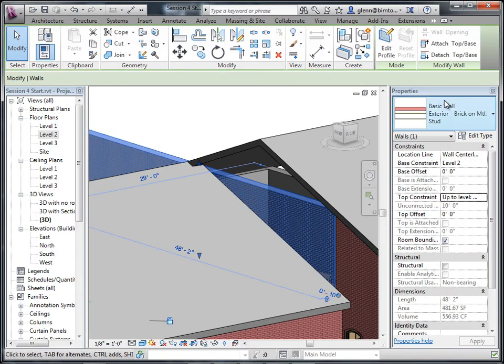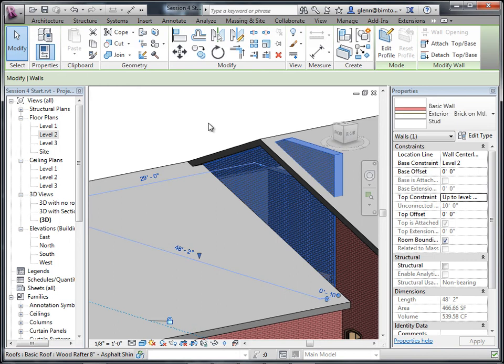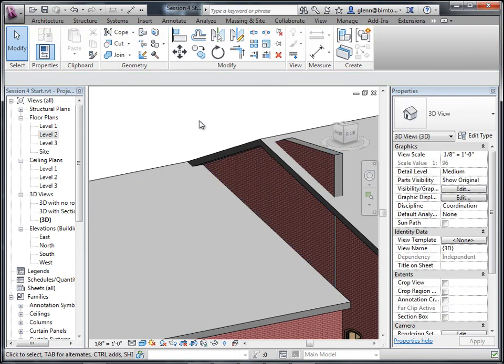One thing we could do is, let's attach this roof to that roof. Okay, did a pretty good job. Not 100% yet, but it did a pretty good job. So let's kind of keep talking about it. Just when you attach roofs, a lot of times you'll get it right. Every once in a while, you get it wrong. It just doesn't quite figure out exactly which of the different attachment conditions should dominate, so it's a little bit confusing. So we're going to go ahead and give it a little bit of help.